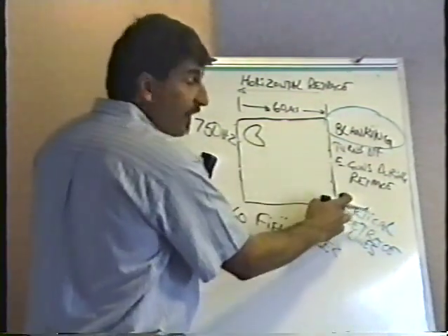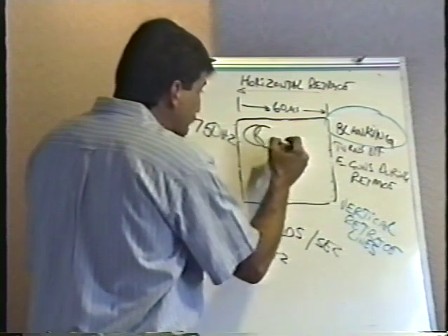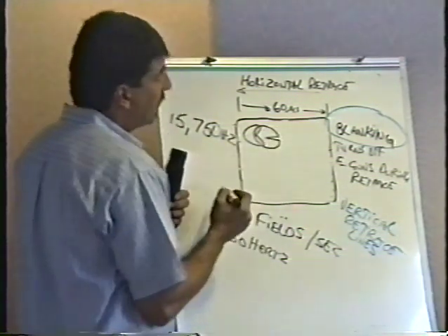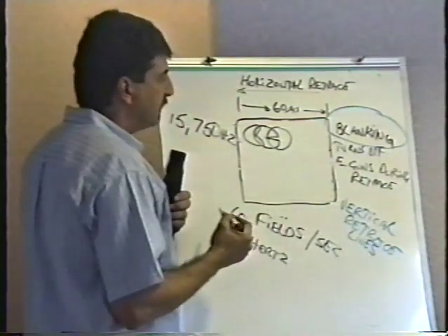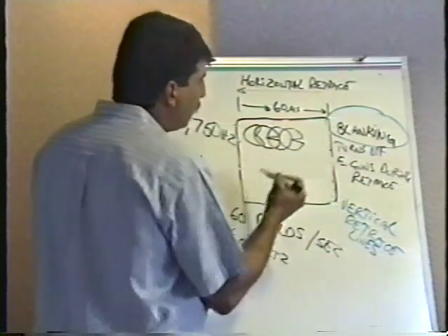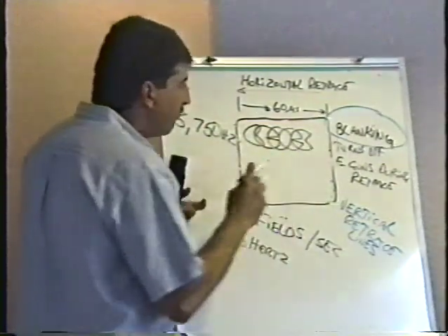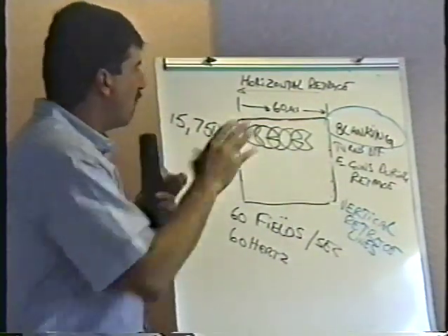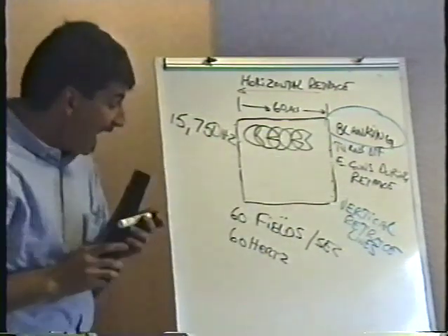Then the beam goes to the end, comes back up. The next time, it draws Pac over here, and his mouth is closed a little more. Goes to the end, comes back. Next time, Pac's over here, and his mouth is closed completely. Goes to the end. Next field, open a little more. Goes to the end, comes back, open all the way. And what we see, of course, is waka. Right? Like that. It's animation.